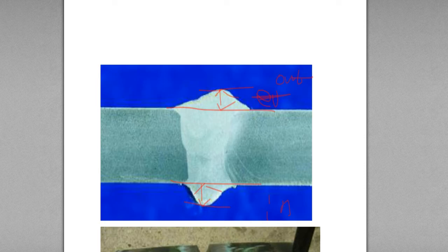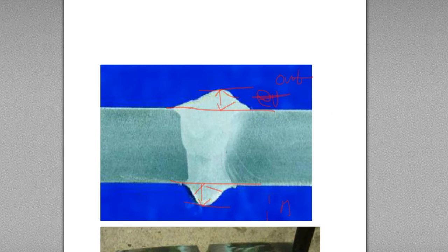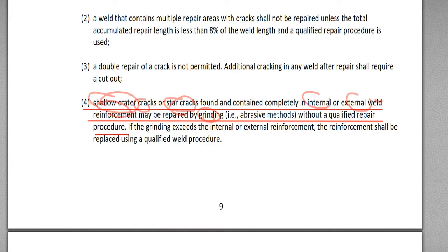And here it says star crack and crater crack may be repaired by grinding, just grinding only, abrasive method without a qualified repair procedure.